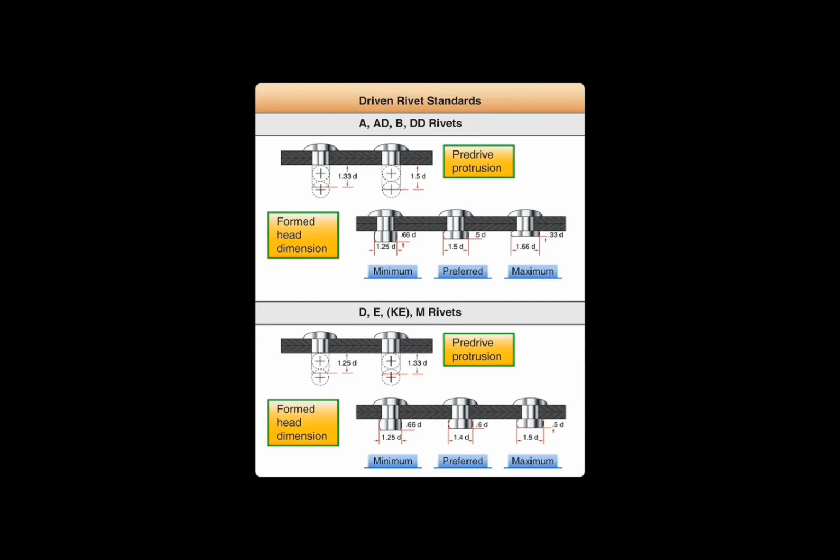What causes honeycomb structure to delaminate? Moisture. What are the acceptable repair methods for bonded honeycomb structures that have been damaged? Potted repair method, laminated glass, fabric, cloth overlay.